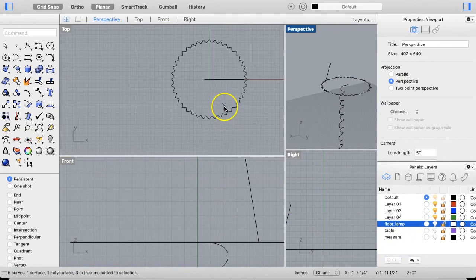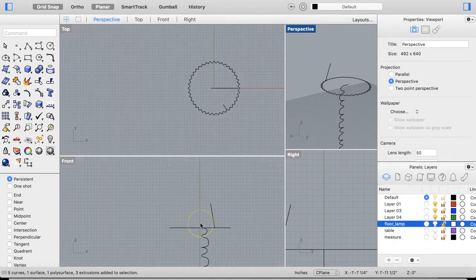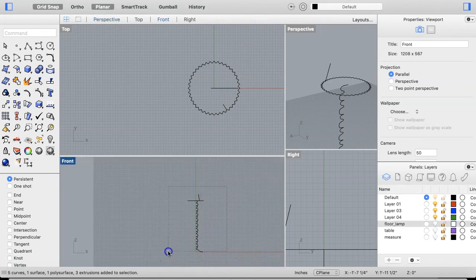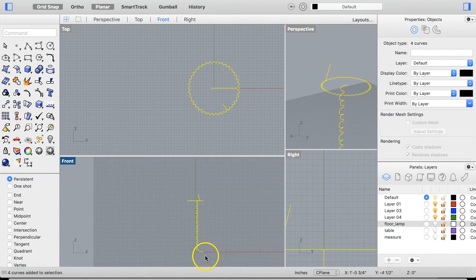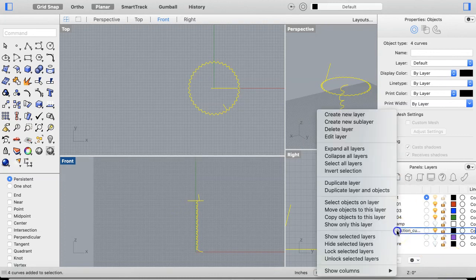Yes, and so you may notice that we have all these curves left over. If you want to make big changes to an object that you've made, I find it a really good idea to save all of these curves, because then if you need to reconstruct any of the surfaces, you can go ahead and do that. So I actually keep a layer in my Rhino files called construction curves. Okay, and I'll move that in there.